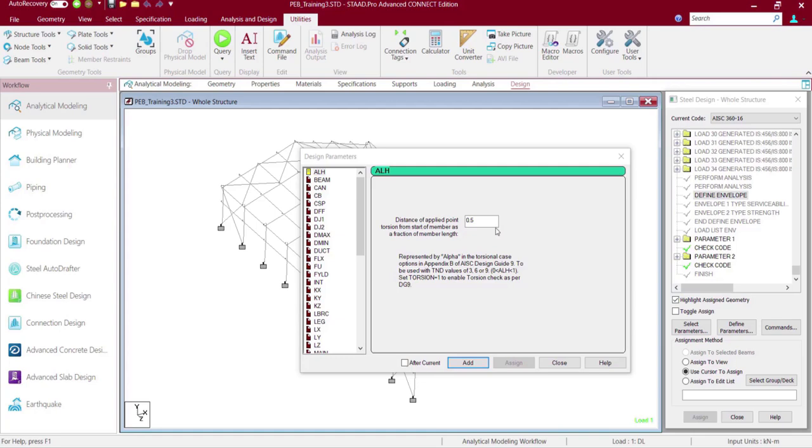Okay, now you can see there is a list of parameters. Now I'm not going to discuss all the parameters for AISC or Indian code. I'll just show you a few of the important parameters which are meant for the PEB. Basically, most of the parameters would be required, like FYLD. If it is default, like FYLD is required if you do a built-up section or hot roll section.